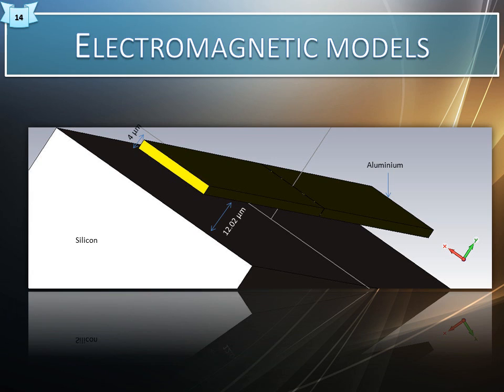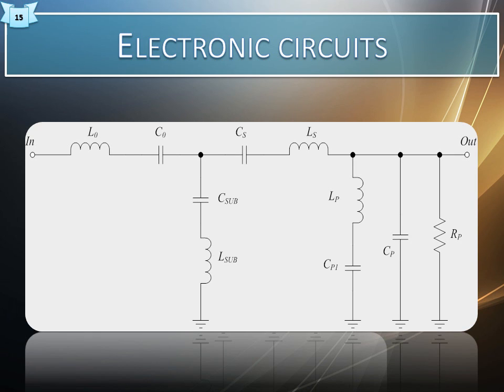The dipole antenna conductive strips are placed on a silicon substrate, on top of a silicon dioxide passivation layer with thickness governed by the 130 nanometer process as shown. This height above the substrate is 12.02 microns. The addition of the substrate represents a more practical representation of the dipole operation, since without the substrate the antenna would only be suspended in the air. These effects are however noticeable in the antenna operation and need to be accounted for in simulations.